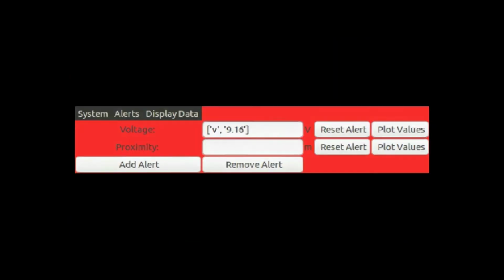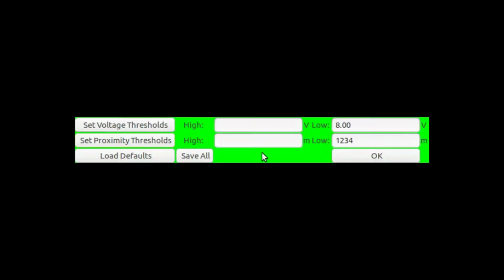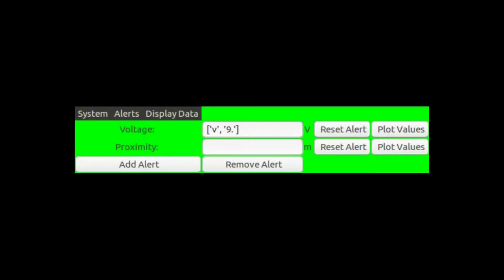The change of the threshold is reflected in the 7-segment display on the ground base unit, and this causes the alert to be activated in both the ground base unit and the main window of the GUI, as some of the values streaming in from the drone are below threshold. The alert can be reset on the ground base unit, and the threshold can be set back to 9999. This also causes the alert to be deactivated in the main window of the GUI.